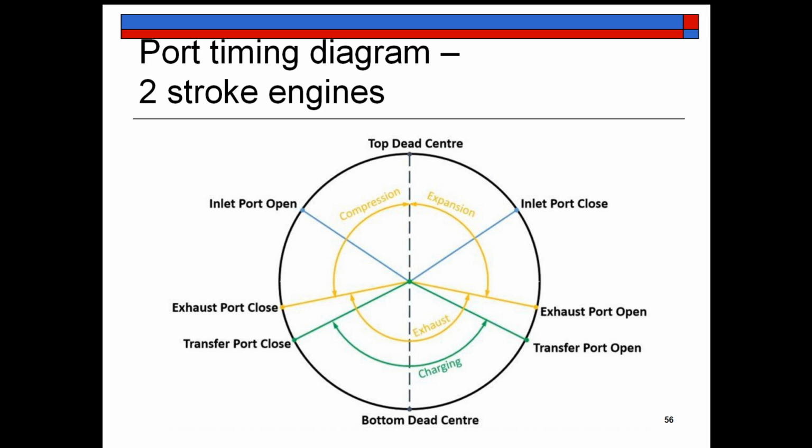Now coming to the port timing diagrams for 2-stroke engines, this is a typical port timing diagram. So you can see the inlet port open here during the compression when the piston is moving from bottom dead center to top dead center.